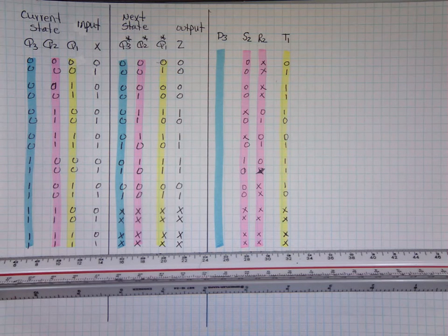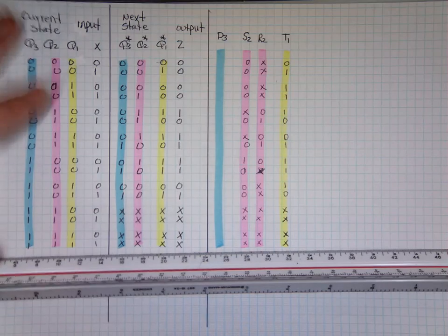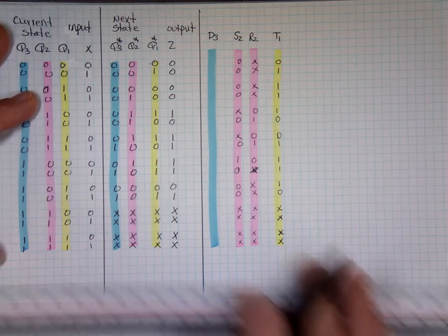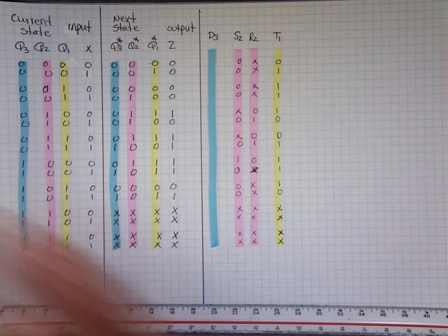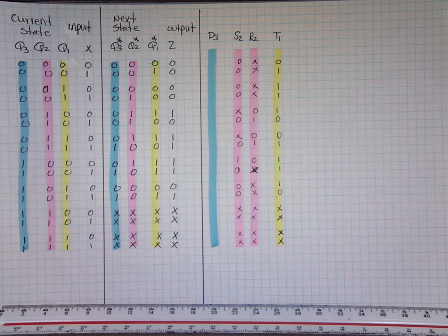But you want it to go to don't care. So we're just going to hope it never hits 1, 1. If it does, Q and Q naught will both be the same. That's the only problem with it. It's not like the system is going to explode. Because Q naught, there's Q1, Q1 bar. One's supposed to be 1, one's supposed to be 0. If one is 0, the other one is 1. When you put 1, 1, you're not going to have 0 and 1. You're going to have them the same. How can it be a bar if it's the same? That's why we don't like it.